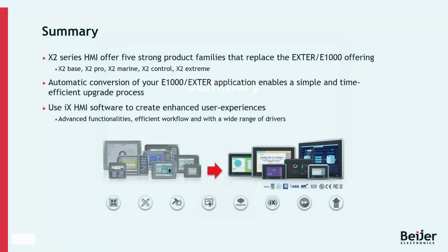To sum up, with the help of iX Developer's built-in conversion tool, it's easy to quickly convert your existing E1000 and EXTER projects to iX Developer. Even though the conversion is not one-to-one, you will save many hours of engineering compared to building a complete HMI application from scratch. And remember, iX Developer includes many new and modern features compared to E1000 and EXTER, so take the opportunity to review what iX Developer is capable of and take your HMI application to the next level.